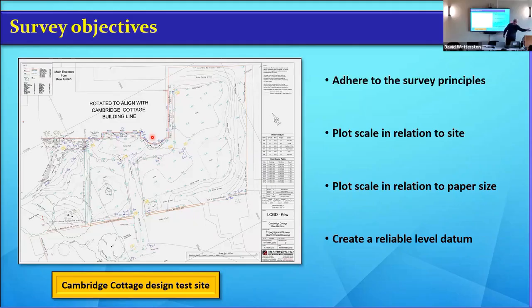So you can't go back to them and say, actually, that wall's 5 mils out of position, because it's 100 scale, which is 30, 40 mil. Okay. Because I said it was 150 mil at 1:500. This is a fifth smaller. 5 into 150 gives you 30 mil. So the line work you can scale off of that drawing, no, you can't get it better than 30 mil. All right, because you just can't get it.